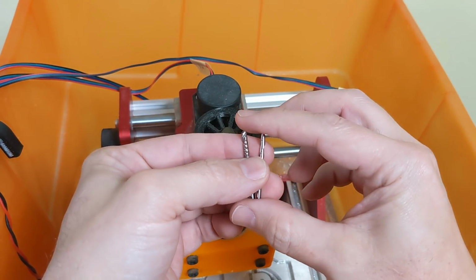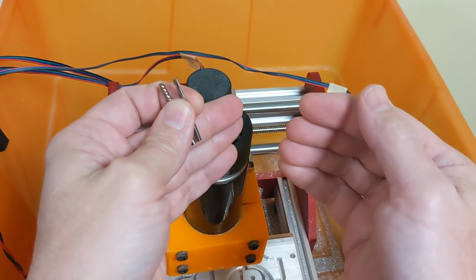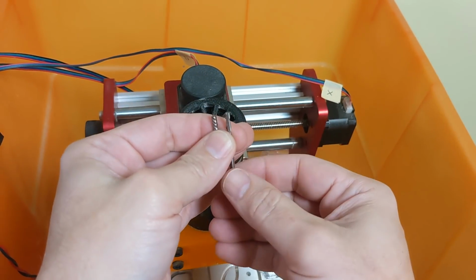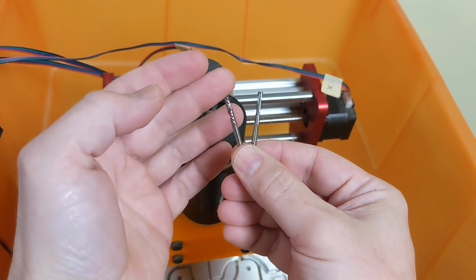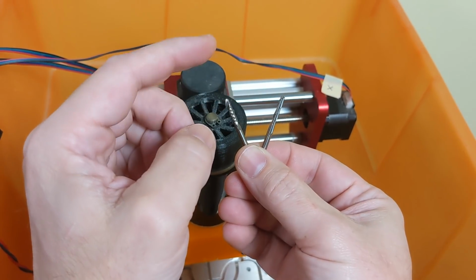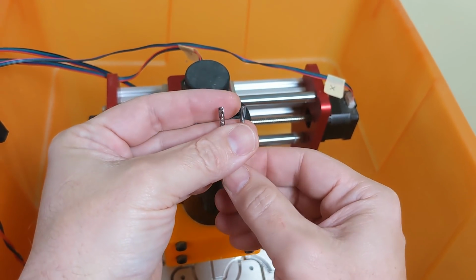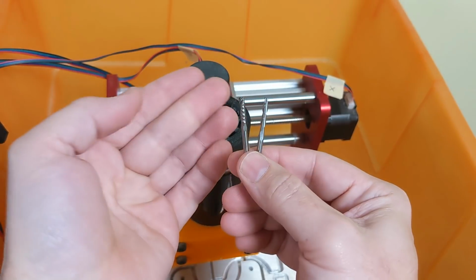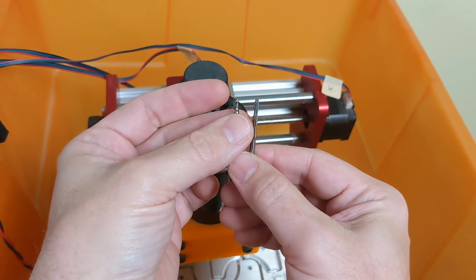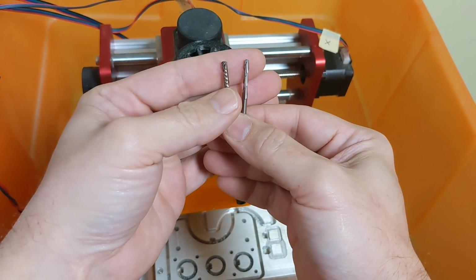So there's a sweet spot in metal. There's an optimal speed, it's called inches per minute or whatever. You want the cut to happen with the feed. There's a balance there. You can't just sort of force it through. So the optimal speed to cut with a single fluted bit is going to be, well, half as fast as a double fluted bit. So there's an interplay there that's very important, and you need to look up feeds and speeds on a table, or you need to get a program to tell you the optimal feeds and speeds. It's basically the core of successfully cutting metal, is getting your feeds and speeds absolutely perfect.